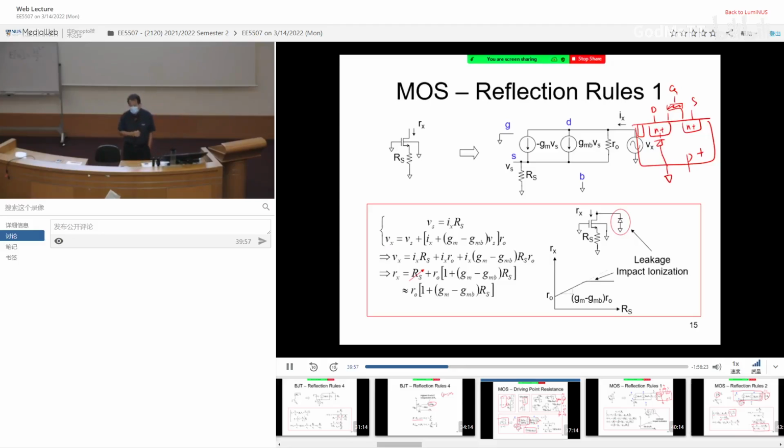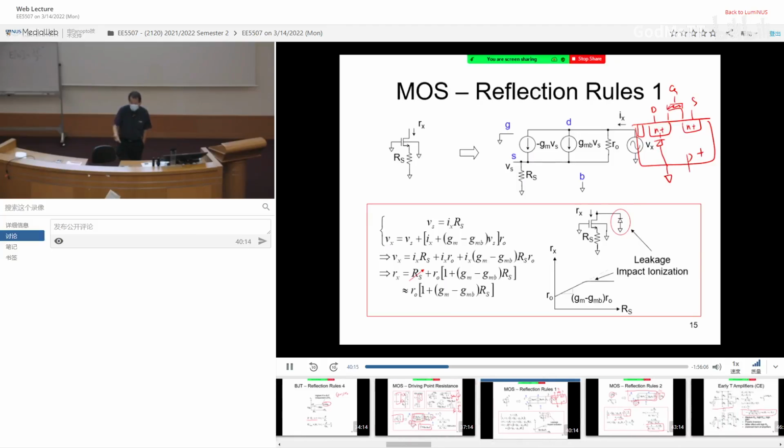Right? Now, for all practical purposes, let's say the transistor is operating, usually it draws current in milliamperes. And since the diode is reverse biased, usually you only draw current in nanoamperes. So do you care about this diode? You don't care. Reverse bias diode, as long as it doesn't break down, is like an open circuit because the current is so small, right? But now, if you try to make the resistance so big, let's say the resistance is reaching gigaohm.